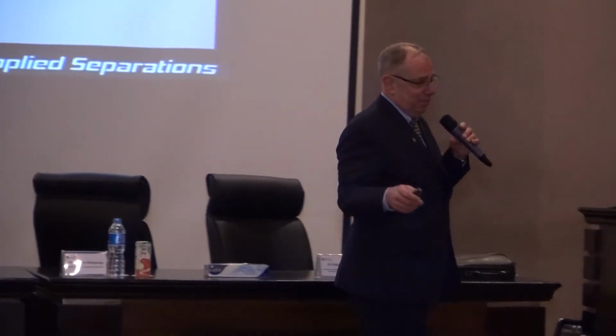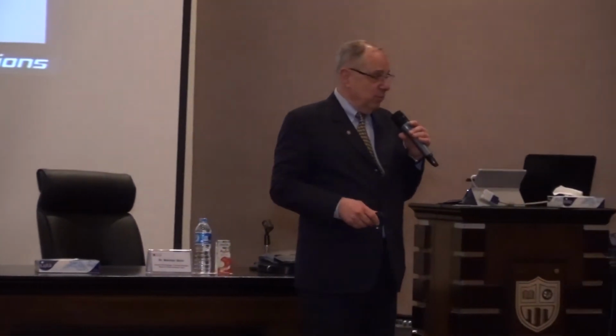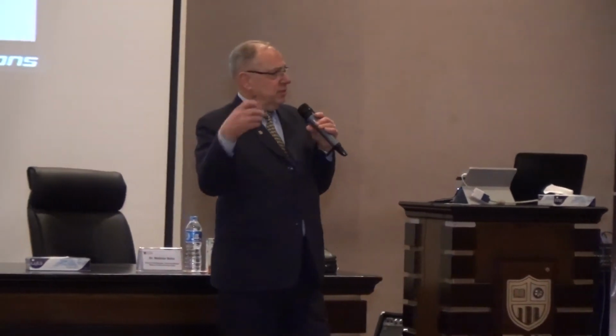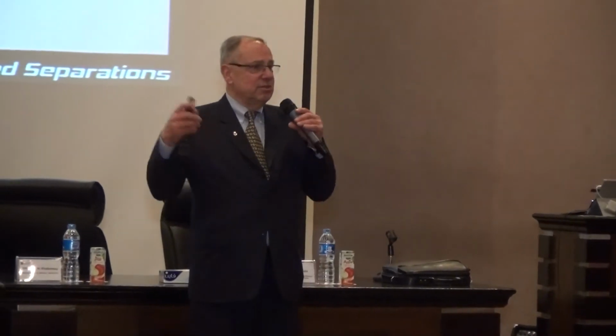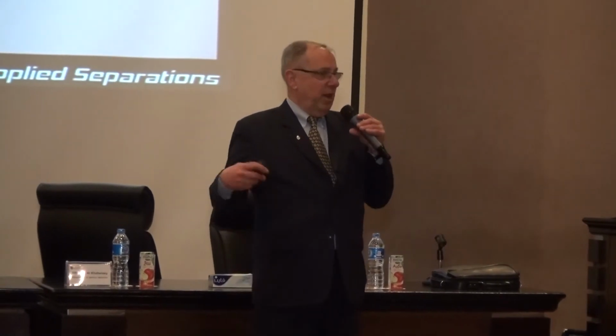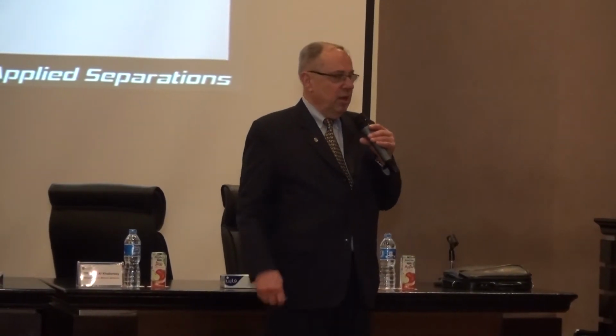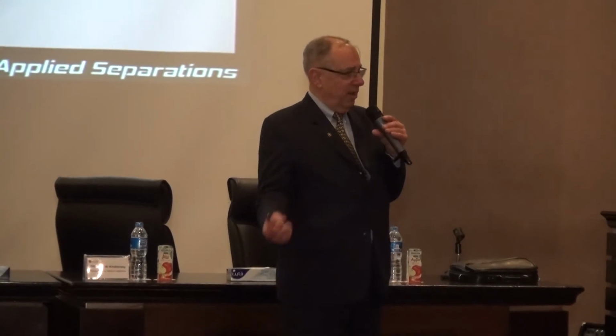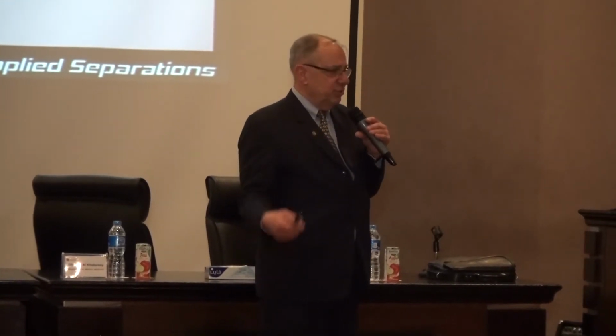Obviously, there are problems with supercritical carbon dioxide as well. I mean, nothing comes without some disadvantages. Of course, there are some disadvantages. The major disadvantage is the fact that you have a pressure vessel. You have to deal with higher pressure. You can't do this work under ambient state. That is the major drawback.